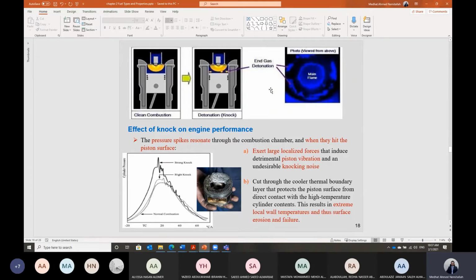If we have water at, let's say, 30 degrees C, and we add heat to this water, what will happen to the temperature? It will rise until we reach the saturation temperature, which is 100 degrees C. So what will happen if I continue adding heat at 100 degrees C? Will the temperature of the water rise? No, it will be fixed, because we will have a phase change. In this case, we call it latent heat. So the heat added to the water will be used just to convert the phase from the liquid phase to the vapor phase.